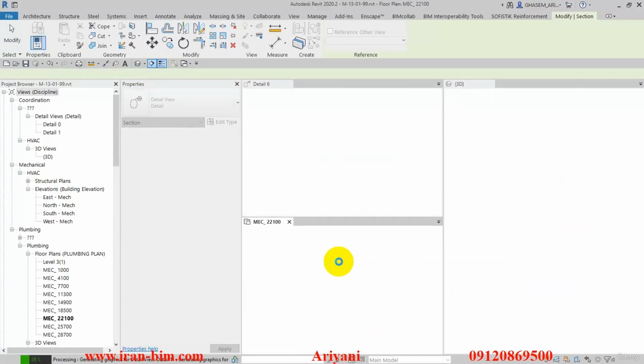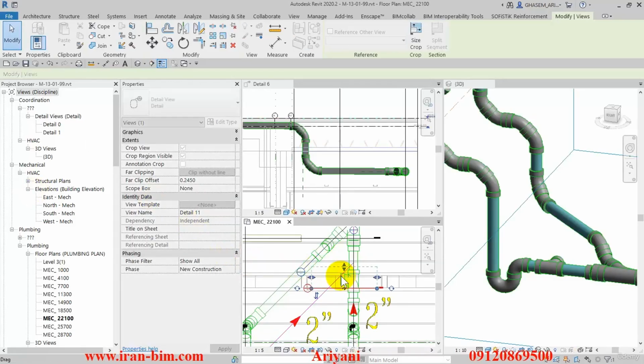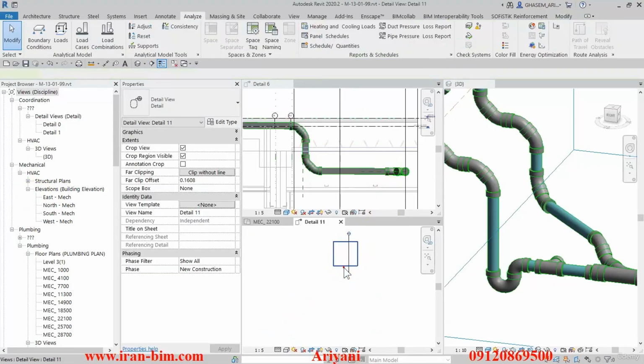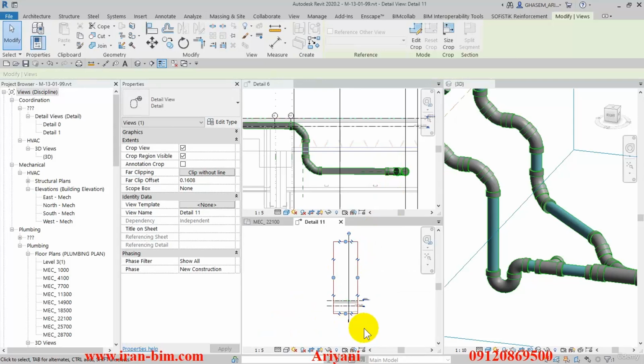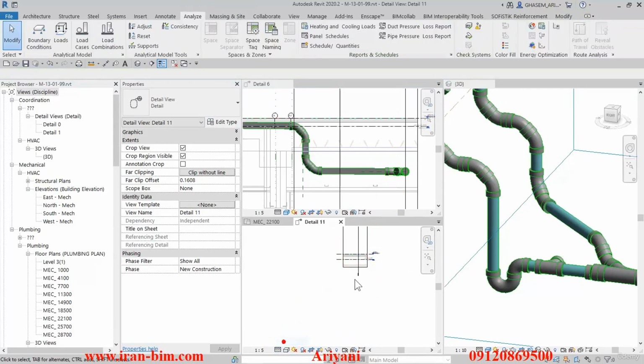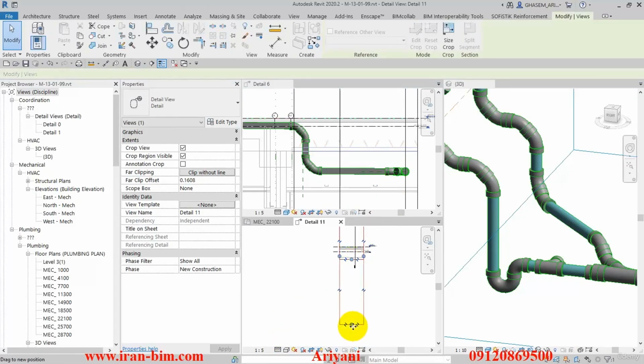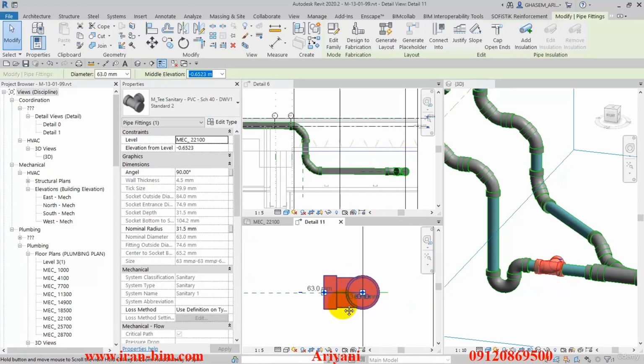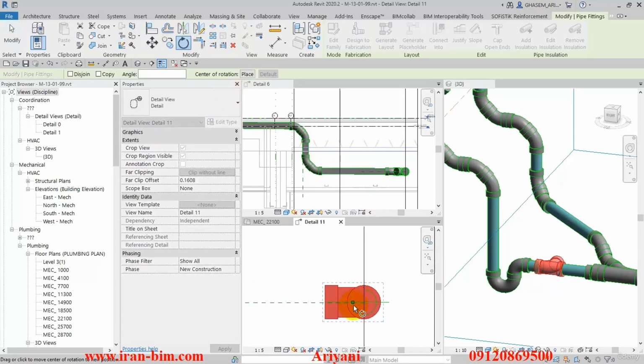Alright, then I'll go here and right click and select go to view, which opens up the cut line for us, and then here we can open this up, drag this down, then we can put the view on fine settings, and then we can open up the view to see what we have right here. So it's right here where we can select the rotate tool and then rotate this based on the center point using an angle of 45 degrees.